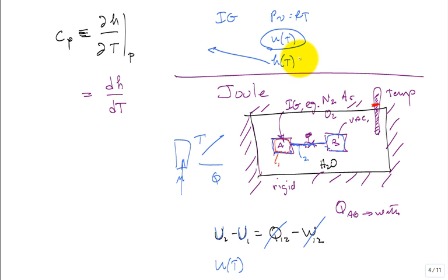Now, once you have this, why is H a function of temperature only? Well, H is defined as U plus PV, true or false? And look what PV is equal to: RT. R is not a function of pressure, volume, or anything. It's not a function of temperature. R is a constant. T is a function of temperature. So basically, once you get that U is a function of T, H is a function of T, true or false? So what we do is, when you have this, you want to unravel that derivative.